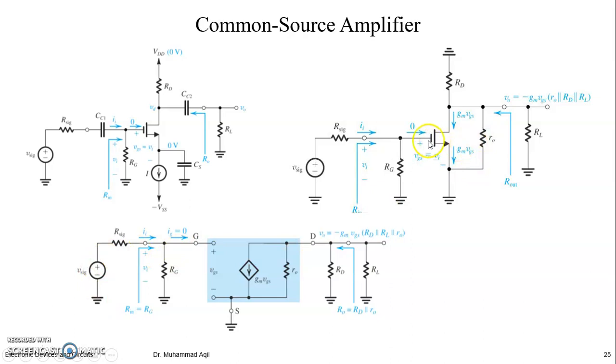You have to be more expert if you are analyzing your circuit directly, but here you can easily see that you have an infinite resistance here, right? But this RG is in parallel with it. So this model is working fine: the signal taken from this port is divided across the parallel combination of these, and RG is what decreases this infinite resistance, right? So Rin is RG in parallel with infinite resistance, and it is actually RG, right?